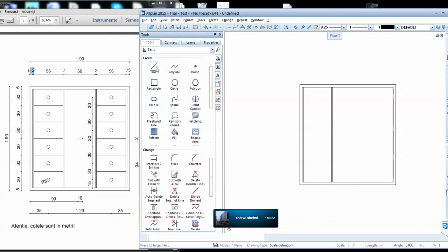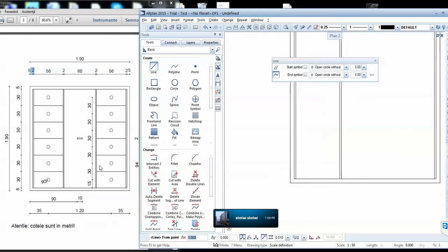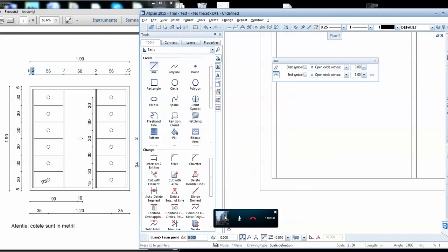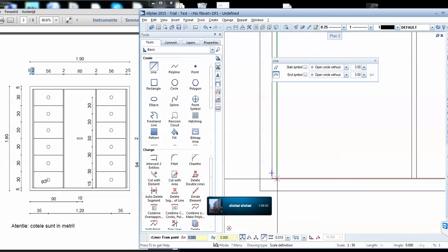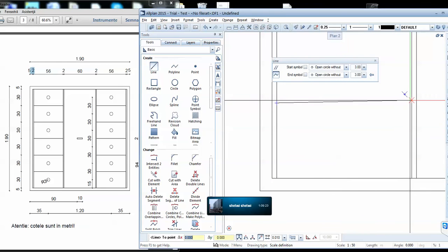I will now do a line to draw this drawer, and I'll use the same relative lines. I'll stay here on this point and then hit the tab to enter delta y coordinates. Okay, delta y, and now I'll say 0.3. I want to start a line here, or extension line here, 0.3. And then I move until I see the orthogonal sign, which means it will snap to orthogonal position on the